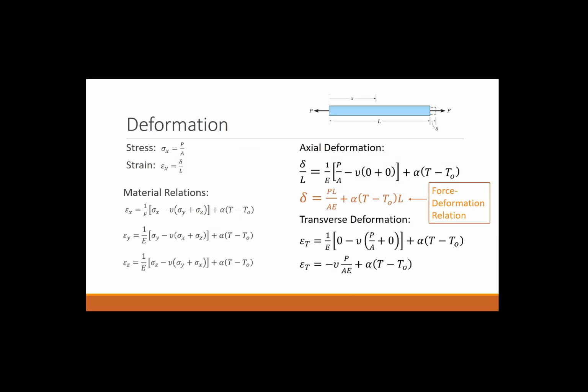All right, so I want to show you how we calculate deformation in axially loaded members. And I want you to see that it is entirely things you already know. Okay, but I want you to be able to get back to this equation if you had to, using the basics. So what I mean by that is you should have ingrained in your mind this stress and strain relationship for normal stress and normal strain. So we say P over A for our stress, and we say the strain is elongation divided by initial length.